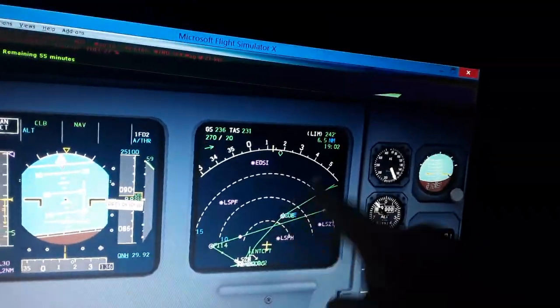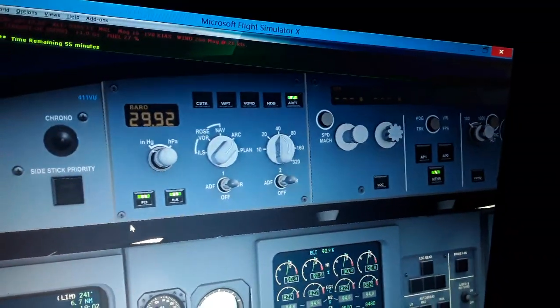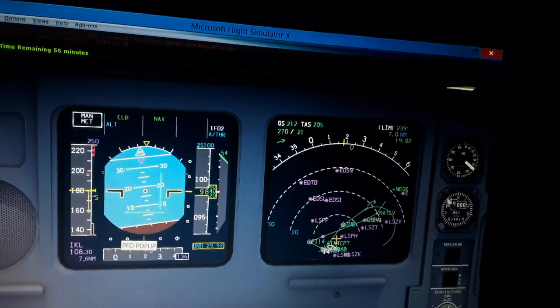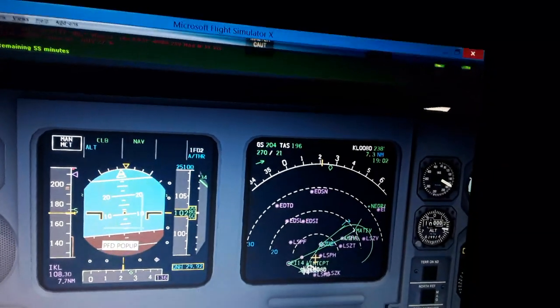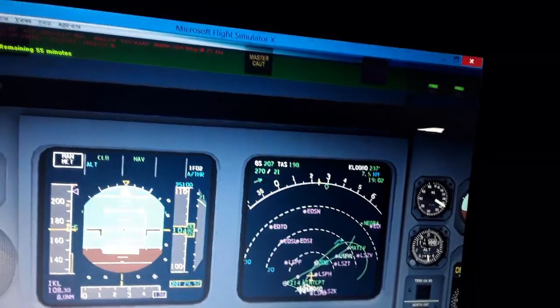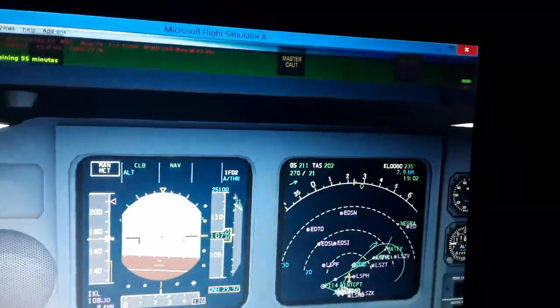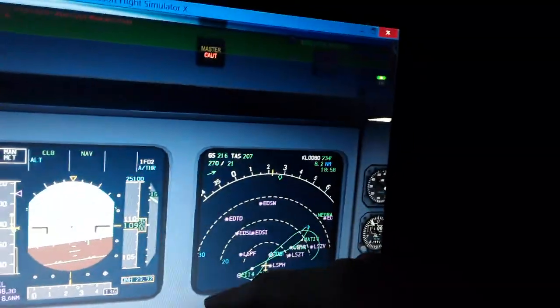You can see here the flight plan. We're gonna follow, maybe use a little bit more range to the 40 nautical miles. We don't need to climb so fast right now. This is the managed speed right now. So I'm gonna retract the flaps to increase the airspeed margin. You can see the stall speed here, the yellow tape over here.